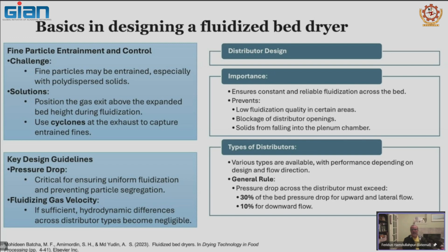You need to, of course, ensure that whatever you do, it will cost you the minimum pressure drop throughout the bed. The higher the pressure drop, the higher the energy requirement for your blower. So make sure that your design will.